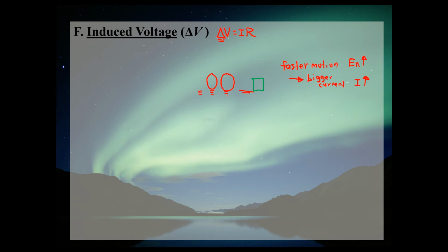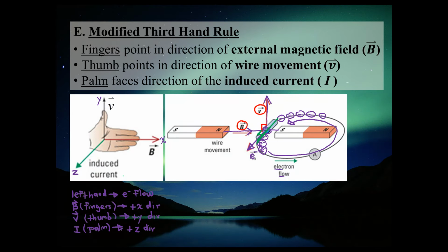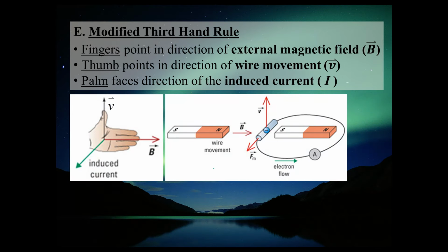So what would that mean if we go back to this picture? This picture's starting to get a bit cluttered, so maybe I could just erase this. There's a couple things you could do that would result in you getting no induced current. If I took this conductor and moved it in the same direction as the magnetic field, in this case the angle theta between v and B is 0, so the direction of motion is parallel to the magnetic field, you don't induce any current. So that's one possible scenario.